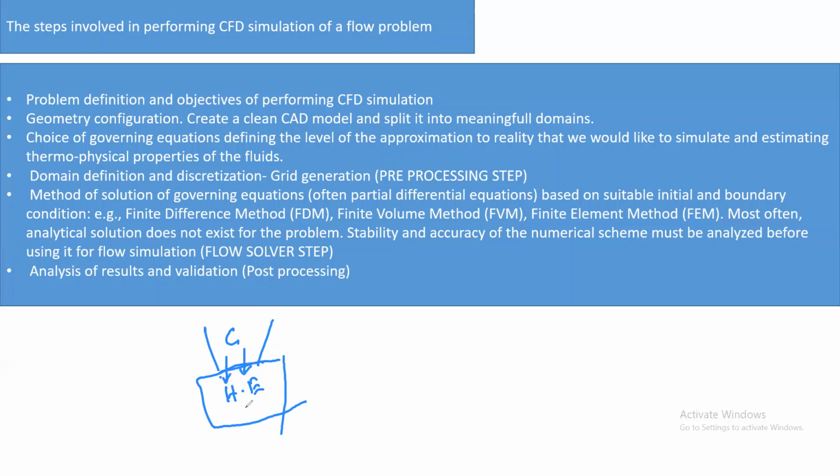When you are allowing the air-fuel mixture to come into the heat engine, you have to calculate the thermophysical properties, like the density, the mass flow, the viscosity. All those properties you have to give correctly. Then only you will get the correct result. At the end, your equation depends on the properties only.